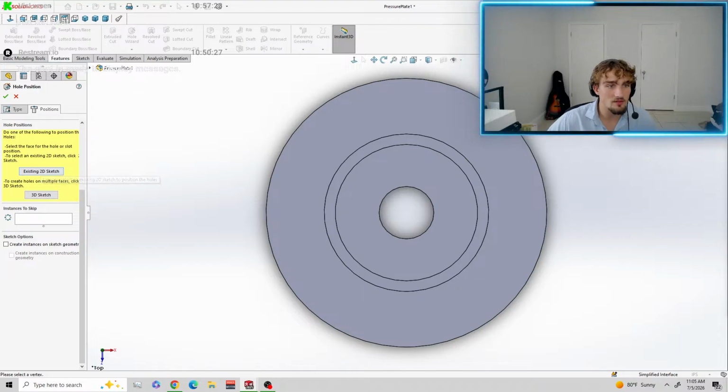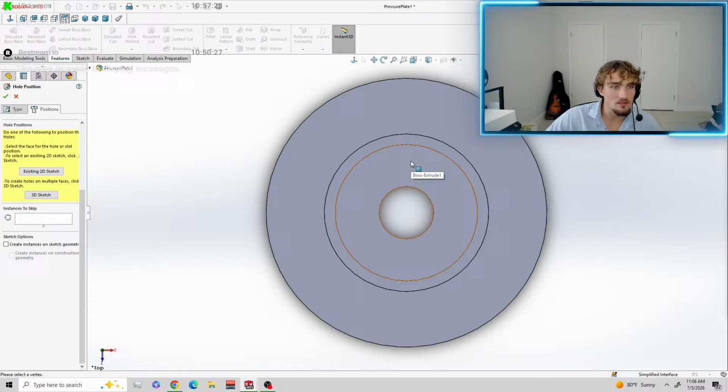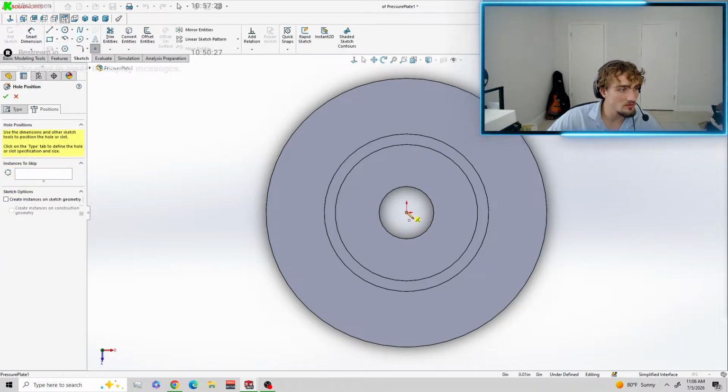In the graphics area, click the base cylinder inside the ring boss. Then click again above the center hole to place a hole. The hole position does not need to be exact. You later move the hole to the center line.